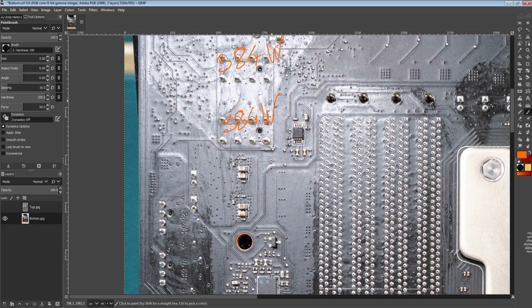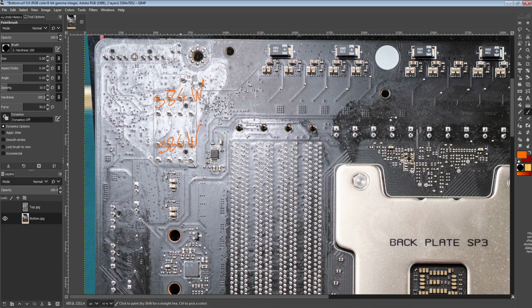Or they should have done what they did on the X299 Creation, which was they had a third 8-pin. Which I don't like the idea of, a third 8-pin. I would have gone for a 6-pin PCIe connector, just because triple 8-pin power supplies are kind of weird. Triple CPU 8-pin is weird, but 6-pin connectors aren't rare. So I would have added just an extra 6-pin and said, if you really want to push the limits of the motherboard, you should plug that in.